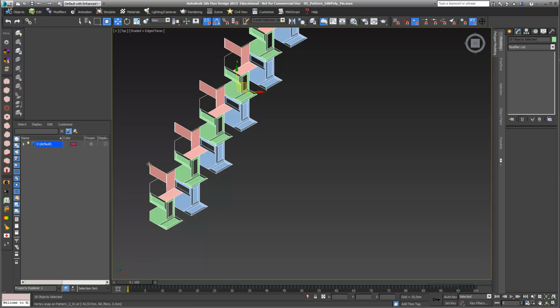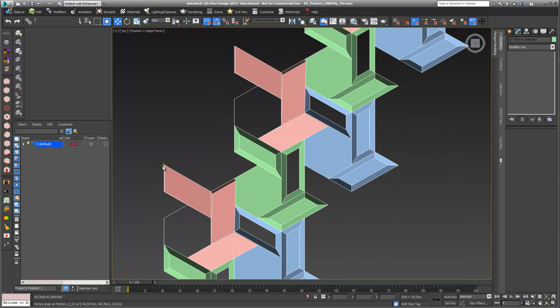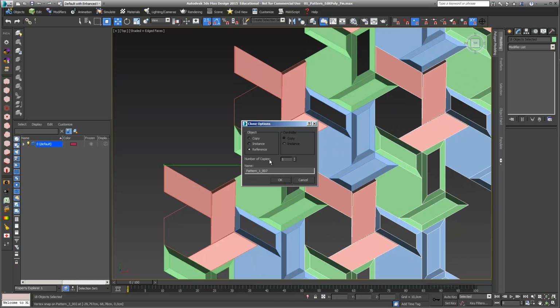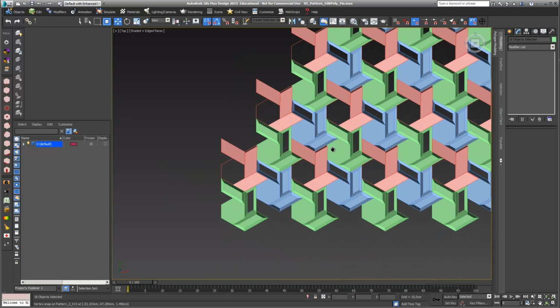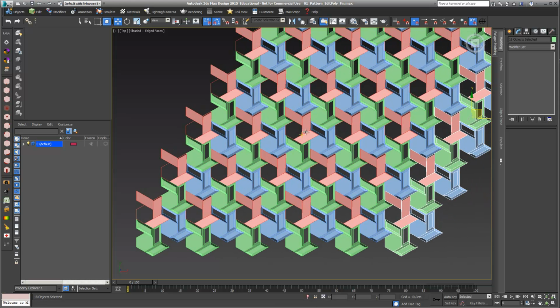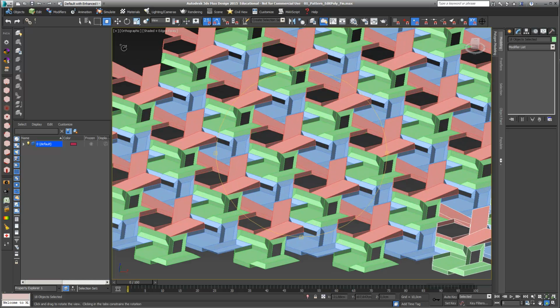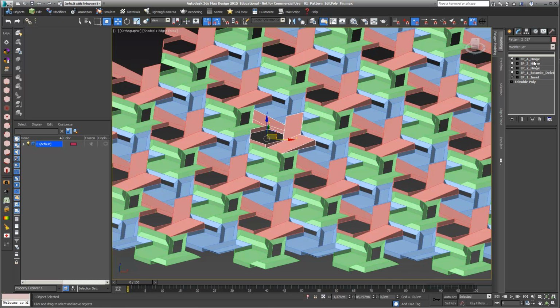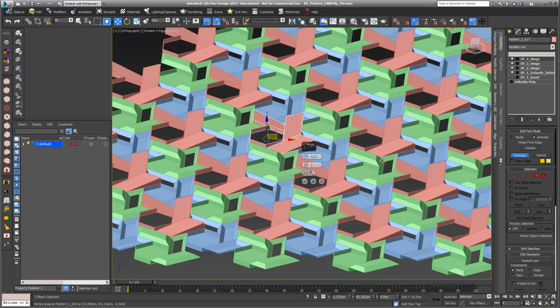I choose the outer corner like this, and hold my shift key again, and as a reference I go into number 5, and here we go. If I choose one of the elements in the middle and turn it again, it's like this. I go again into my hinge number 4, and I can change the radius, and this is expected, but you can see that there's a little bit of a line on top.